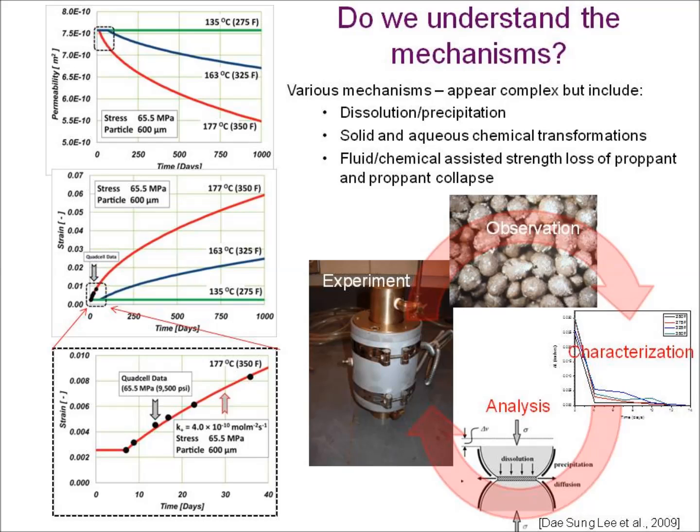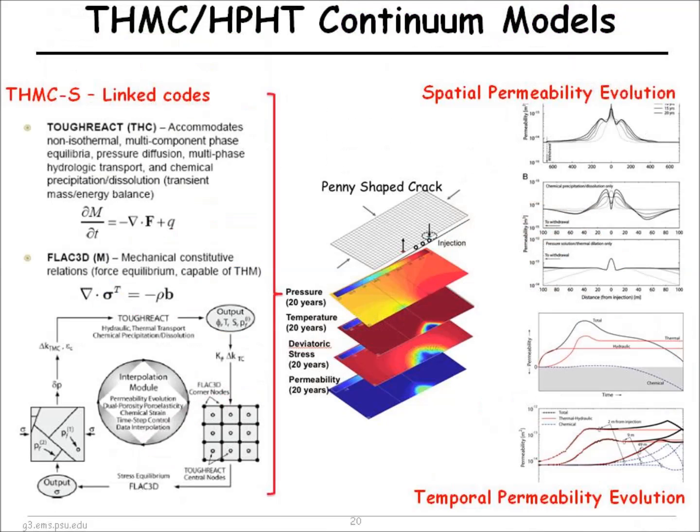There are attempts to link, for instance, measured strains that occur during the compaction phase over just a bit more than a month into strains which you project over longer periods with different temperatures, hotter, cooler, coolest, and then use those to make predictions of how permeability will change over the same kind of time scales, maybe a 20 or 30% reduction in permeability.